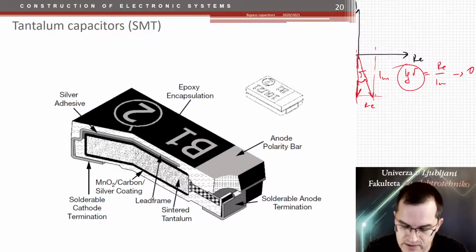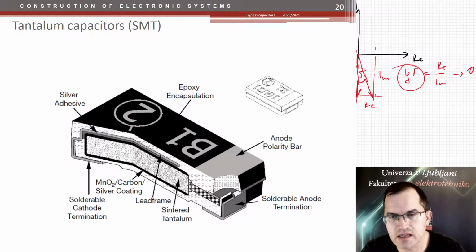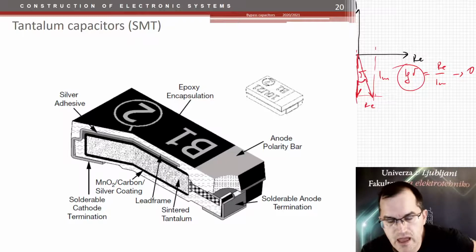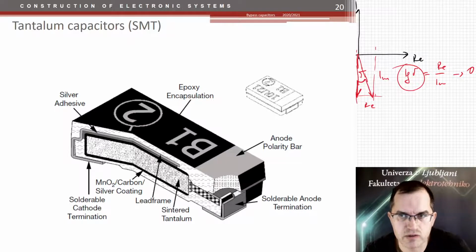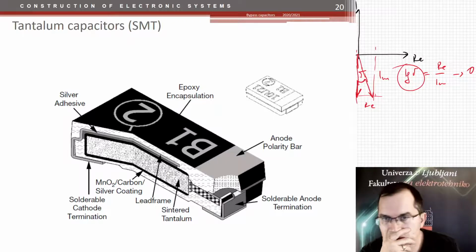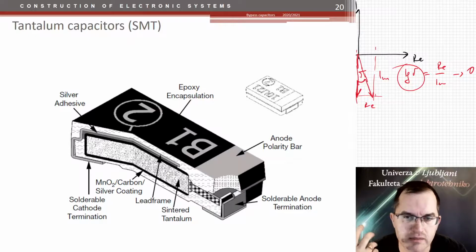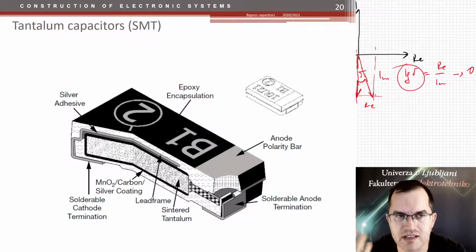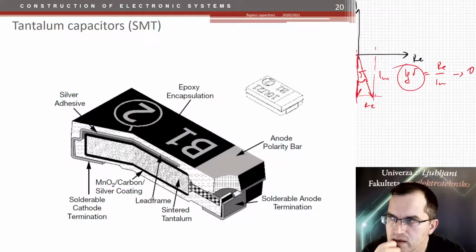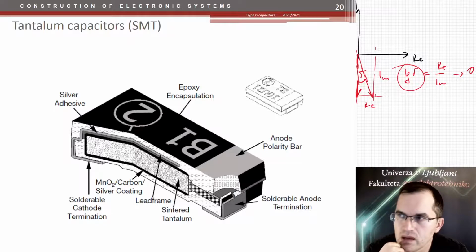What about tantalum capacitors? Well, these are, as I said, very good, but they have some issues, and these issues are two actually. They are polarized, and they are very unstable regarding the lifetime. So they are very voltage sensitive. Higher voltage or reverse voltage would break them immediately. They can explode very easily. So these are not very reliable capacitors. But nevertheless, they are still used, though not very often, I must say.